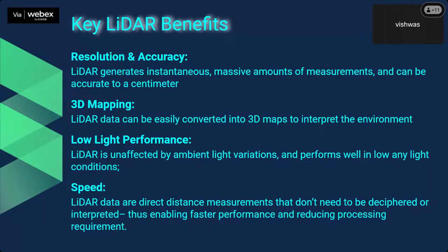Another advantage is that it can be used in low light. Unlike photogrammetry and other systems, photogrammetry requires some light to take a photo. If there is no light, there will be grain. If it is very dark, we can't capture a photo. But LiDAR uses its own light, its infrared light. Since it is using its own light, you can even use it at night or in any dark weather conditions.